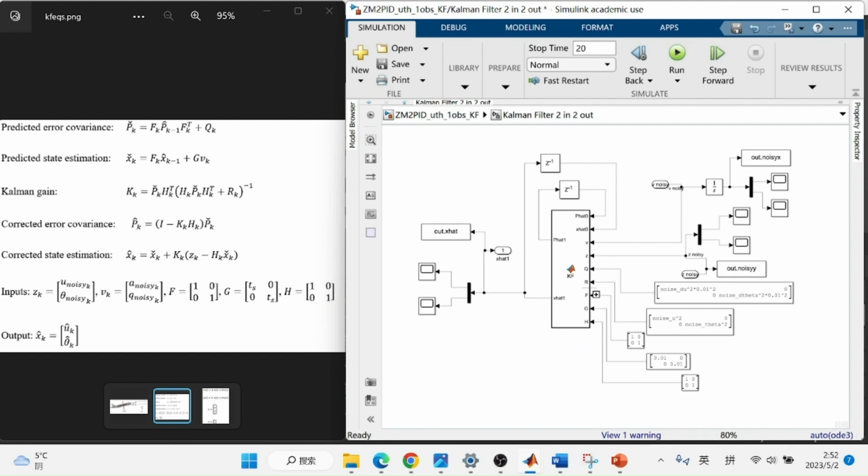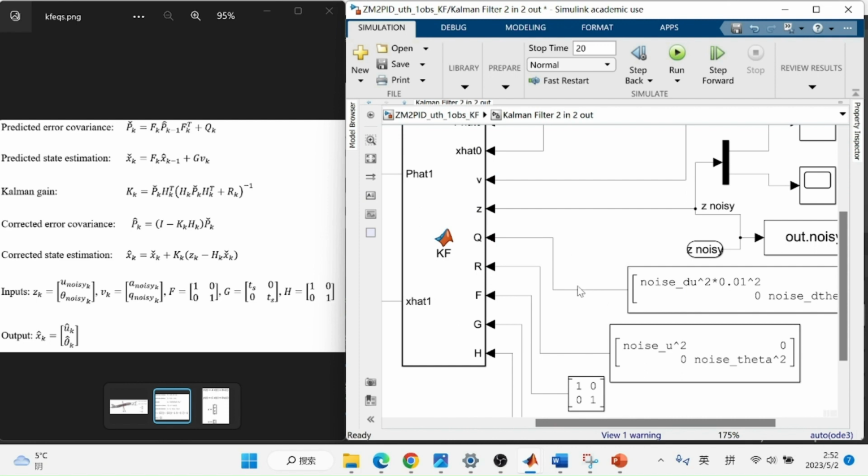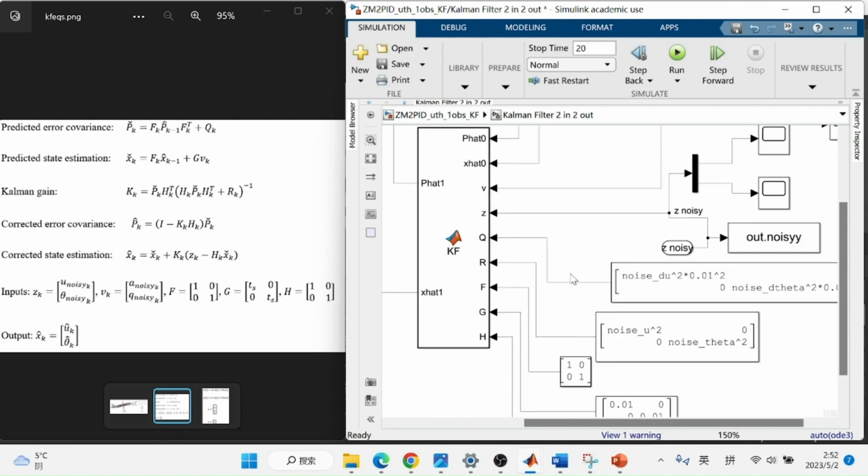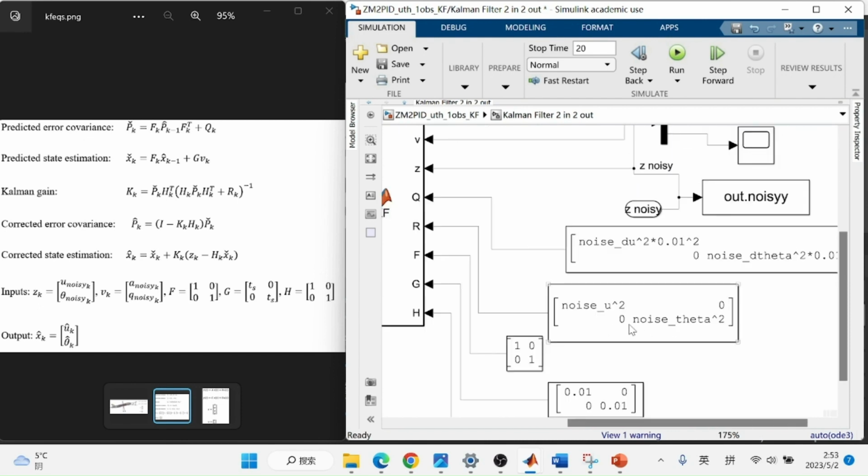Now let's talk about the covariance matrices Q and R. They are basically squares of the standard deviation of the error per one time step for each set of sensors. R is for the axial speed meter and the pitch angle meter and is straightforward, which is basically the square of the standard deviations in the sensor errors that will directly result in variance.